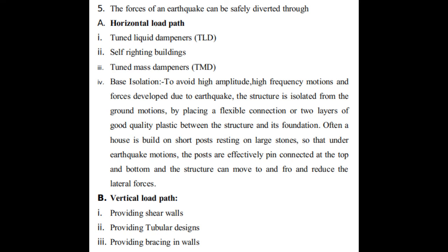Sometimes a house is also built on short posts resting on large stones. So when the earthquake happens and the motions occur, the posts are effectively pin connected at the top and bottom, and the structure can move to and fro and reduce the lateral forces. So the structure can be saved in this way also. Under the vertical load path, providing shear walls, providing tubular design, and providing bracing in walls, the forces of the earthquake can be diverted.